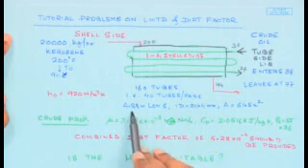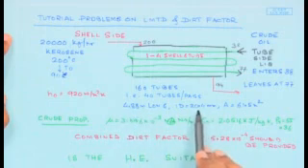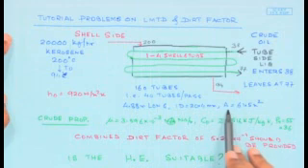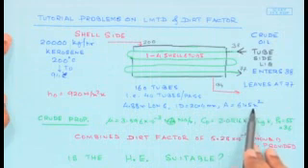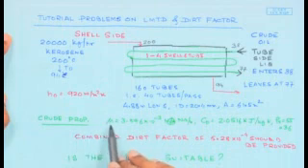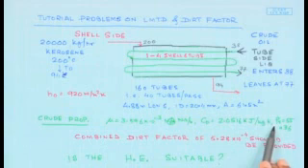The tubes are 4.88 meter long. The internal diameter is provided, and the total heat transfer area of these tubes is given as 61.5 meters square. The properties of crude oil, which provide the viscosity, the specific heat, and the Prandtl number, are given.